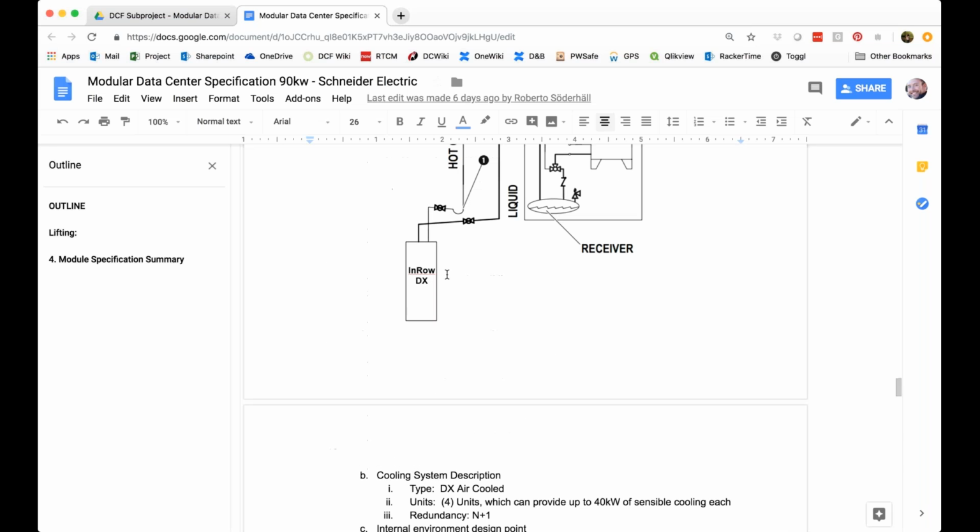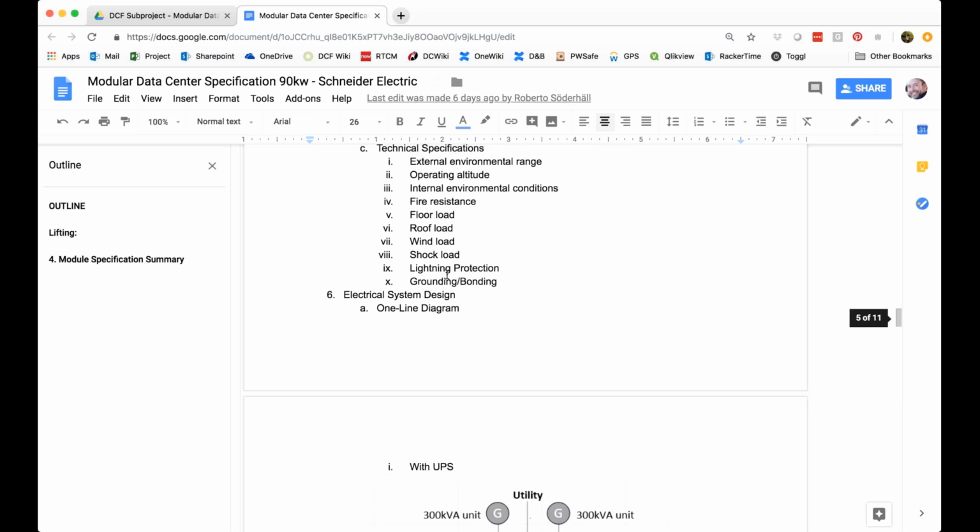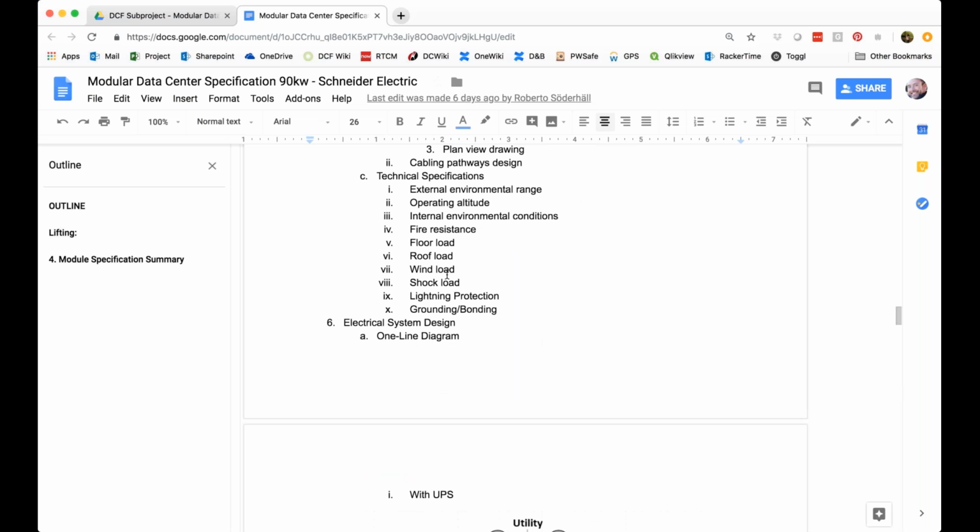At the moment, if we have to say today, today is direct expansion at those capacities. But if I have to think about tomorrow, then there are some questions, because at the moment the proposal from the compressor manufacturer is for flammable refrigerant, and the feedback we are getting from the data center is that they are not happy with flammable refrigerant inside the white space. So although the new stuff is less ozone depleting, the problem is they've become more flammable. Is that true?